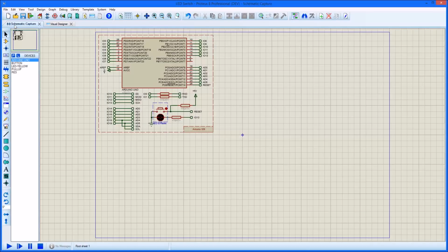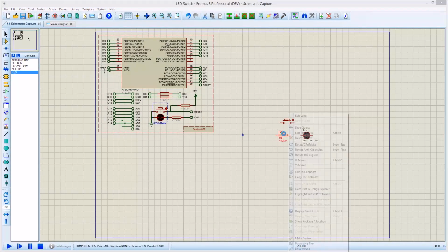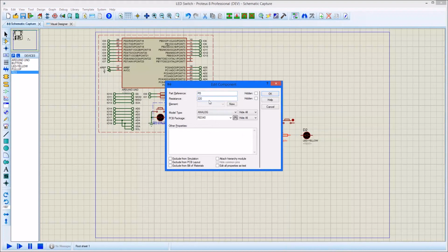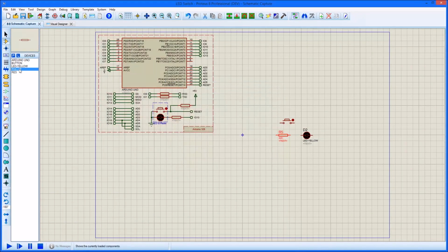We now need to draw and connect this on the schematic. We won't go into detail here, as schematic entry is covered in depth elsewhere. Switch to component mode and place the button, an LED, a 220 ohm resistor, and a pull-up resistor in some free space. Switch to terminal mode and place a power, a ground, and two default terminals relative to the placed components. Wire up the schematic parts and place a plus 5 volt label on the power terminal.